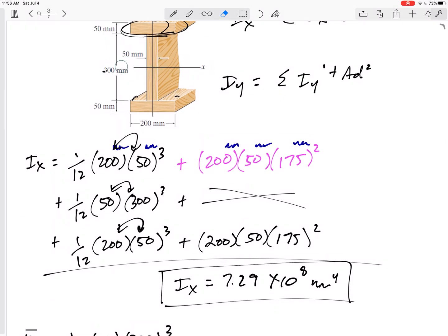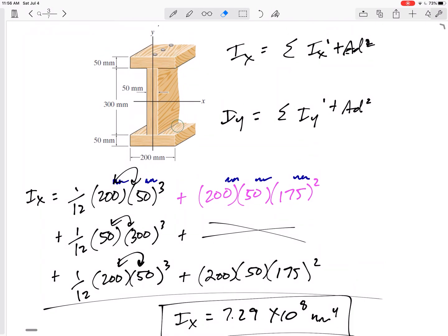It really just means that it would be harder to bend this beam about the x-axis than the y-axis. Imagine this is very large, almost like a ruler. How about an I-shaped ruler? It's easier to bend the ruler about the y-axis than the x-axis. Well, it's really column buckling, if you think about it. But well, it's really stress. Okay, don't worry too much about that.